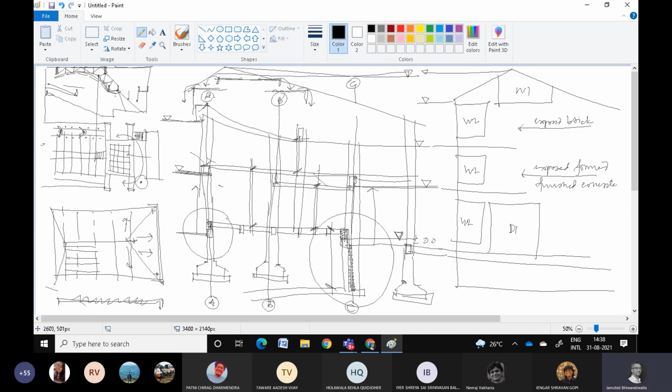All the window and door nomenclatures will have to be seen, and all the relevant details, be it beam bottom levels, floor levels, or peak roof details, will have to be seen in the elevation. The elevations will preferably be of all four sides, with all these types of nomenclature.